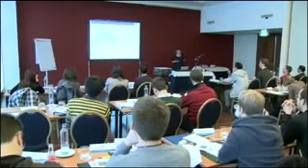But that's not the only reason why we use clay, which has silicon, alumina and iron together, because this alumina and iron are very important because they form a liquid at high temperatures, and this formation of this liquid allows the different reactions to occur much more quickly. Okay? So we have about 20%, and there can be other things we introduce to adjust it.